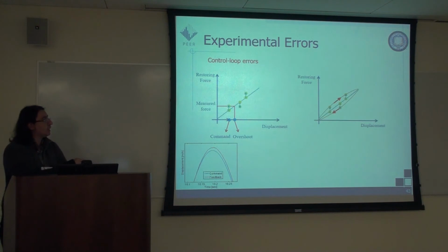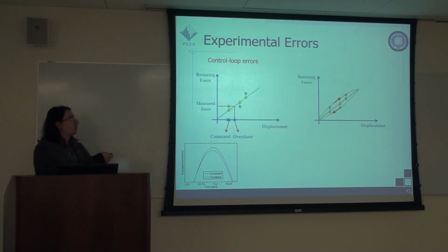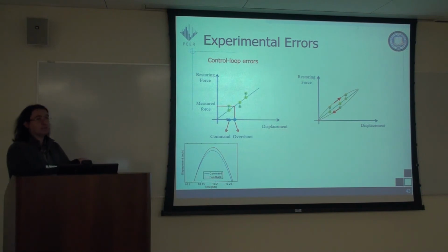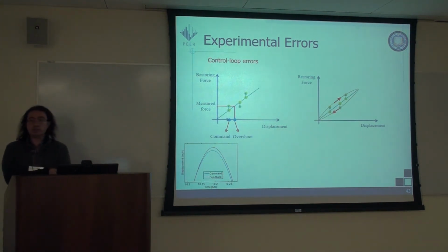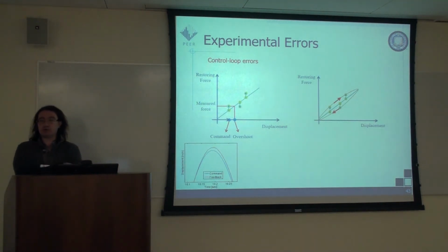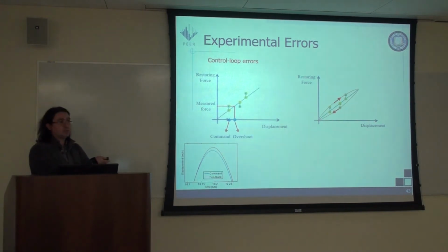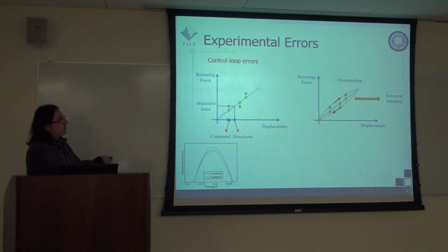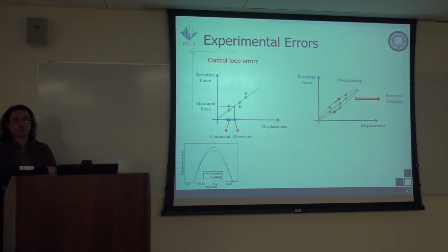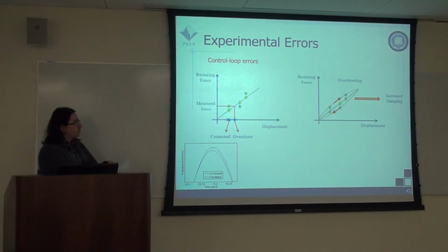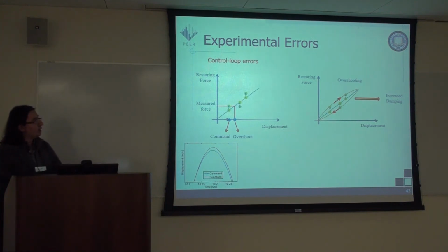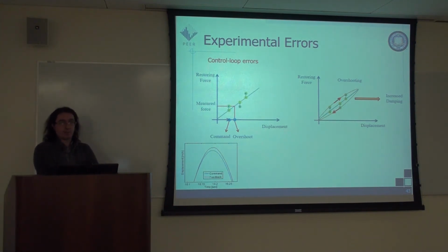So in this case, the hybrid simulation observes a specimen that actually has a linear force displacement as a specimen with a hysteretic loop, and obviously this makes the computations incorrect. But on the interpretation side, this can be interpreted as increased damping. So we can say errors that lead to overshooting or lead in time result in increased damping.